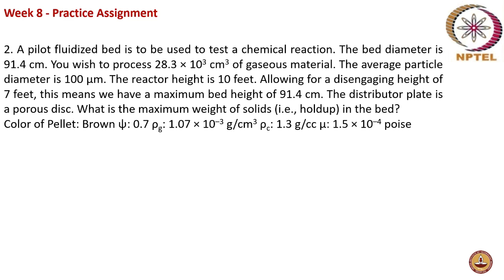And then what happens after 7 feet is that there is a disengagement, that is the disengagement height. That means the bubbles will start disengaging, and there is no more retaining of those things. So the actual bed height where the bed is fluidized is 91.4 centimeter, okay.